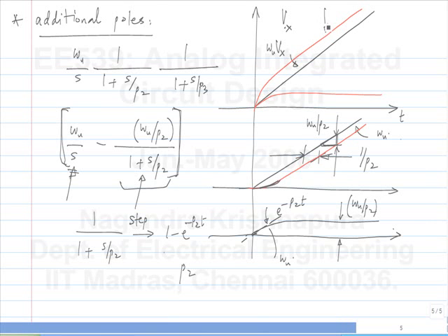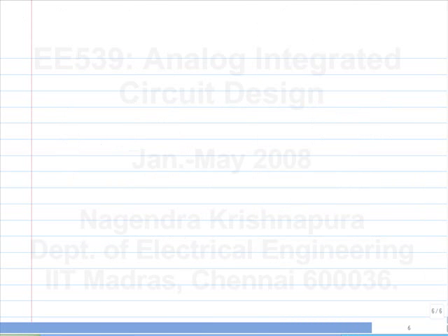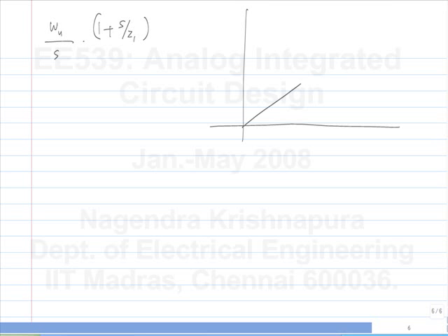So again, we can calculate it quite simply. What's the opinion? I'm not getting answers from most of the people here. What will happen if I have this ideal integrator, and additionally I will have a 0? What is the ramp response? The ideal ramp response again is, for an input Vx, for a DC input Vx, a line of slope omega u times Vx. What am I going to get with the 0?